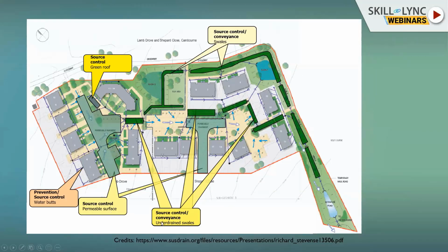Then the other ones were the swales. Swales were vegetated channels. In some cases, they were connected to other swales, and in some, they were just placed independently because the infiltration rates were so good. So we were able to manage just these undrained swales, so that the entire water coming to them gets infiltrated.